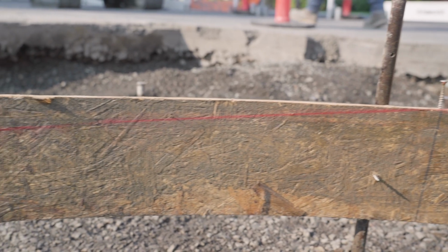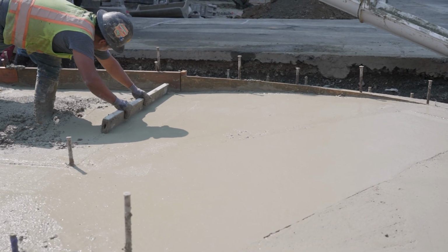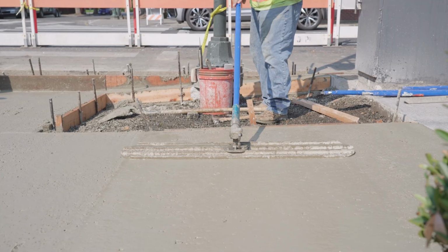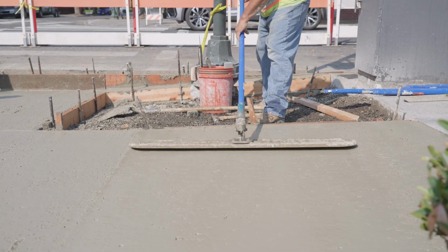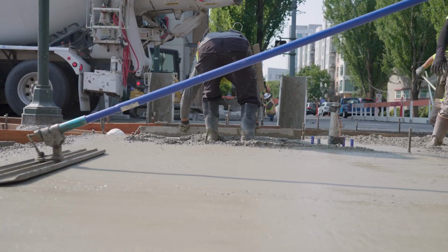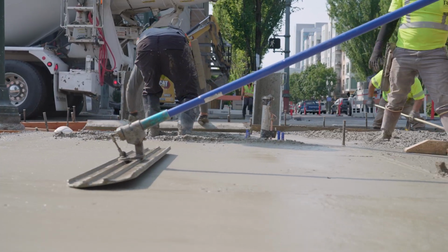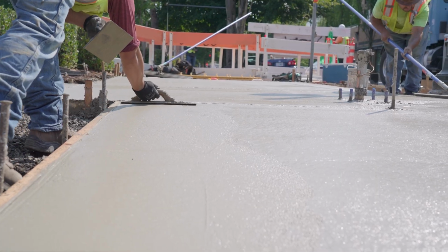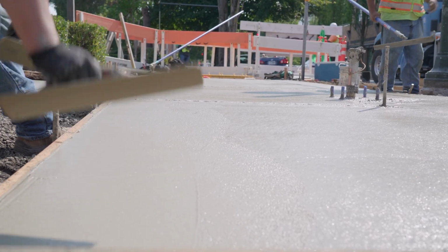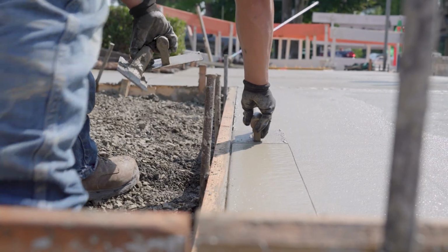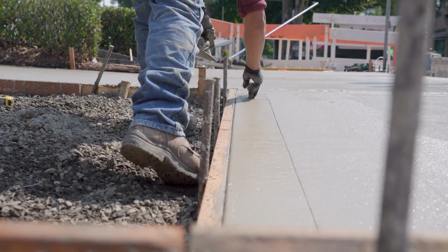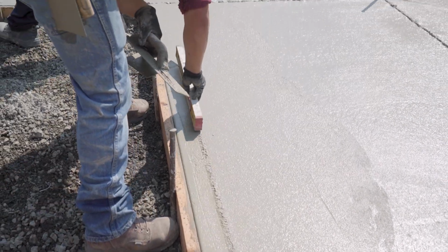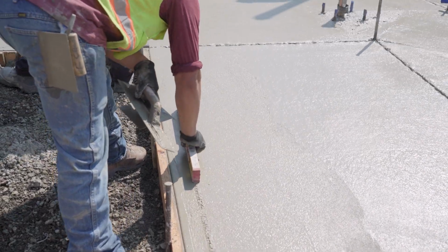Remember that flare line on the form? That extra touch paid off. As the concrete begins to set, waves of finishing begin. Smoothing and leveling, cutting joints, and finally, brooming. Note the attention to detail, always backed up by double-checking levels, because until concrete fully sets, it's a moving target.